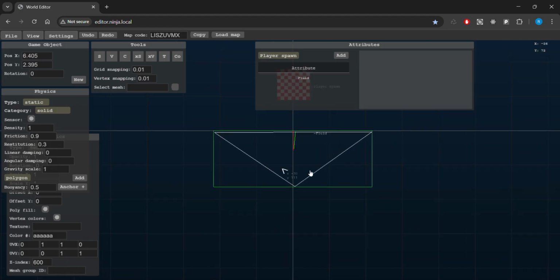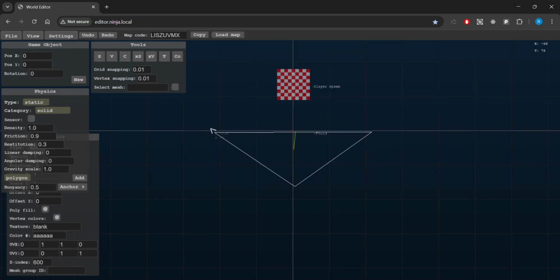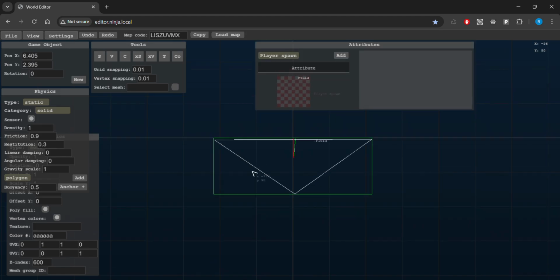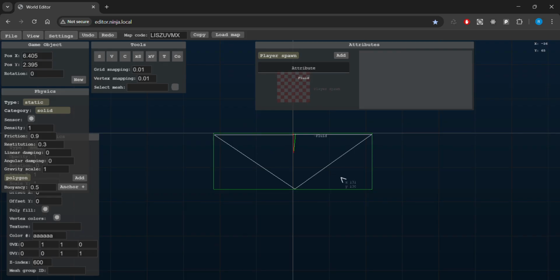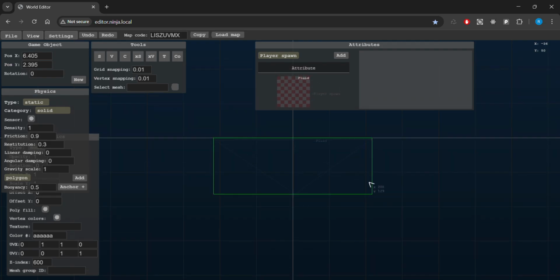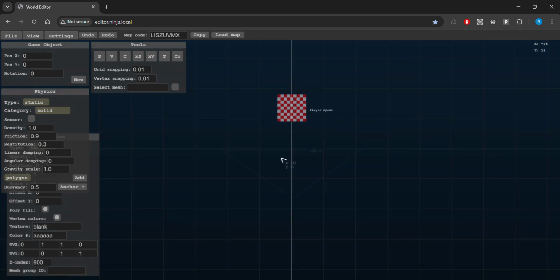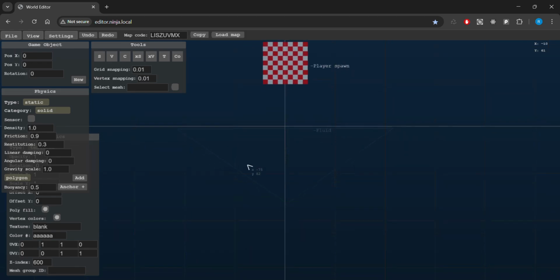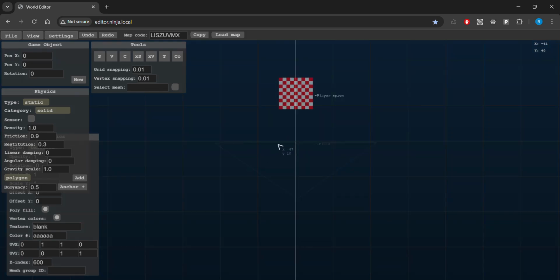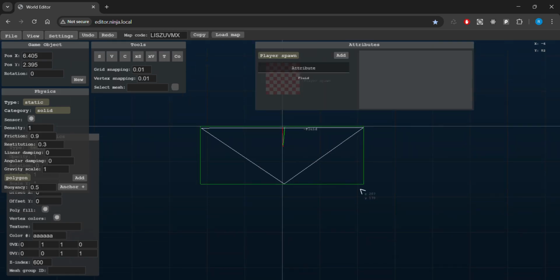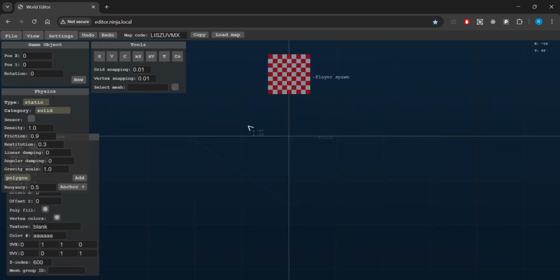So first of all, we're going to add the visual layer on top of this physics layer, and we don't want this physics layer to be in our way. So we select it, and then we press the Alt button, and then we press the L key while holding the Alt button. And this will lock the layer, so it is no longer selectable. It will not bother us. It's still visible, but it's now locked away in the background. If we want to edit it again, we hold the Shift key, press L again, and there it is. And we can select it again, but that's not what we want right now. So Alt key, L, and the layer will be locked in the background.